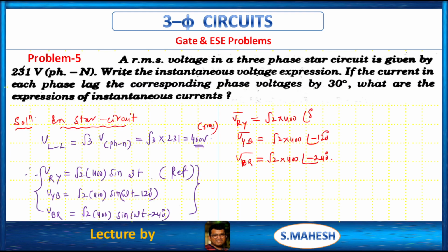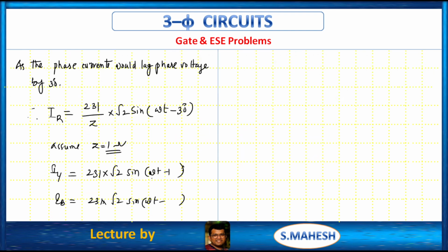Here we are providing the line voltages. So in star connection, line voltage leads phase voltage by 30 degrees, right? Here the line voltage is at 30 degrees, 0, minus 120, like that, minus 240. What about phase voltages? Yeah, we have VR at an angle minus 30. This is minus 90. Okay, I have made a mistake.